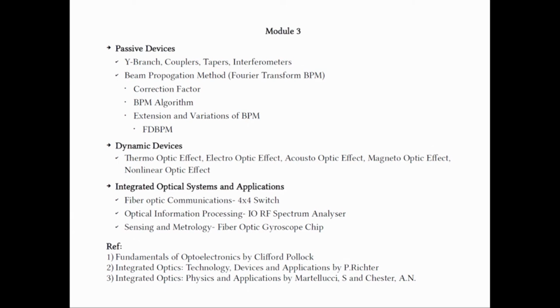They could be used for input output couplers, we can use the acoustic effect for doing a lot of optical signal processing. We can have signals, some of them could be attached to the electrodes, IDT electrodes, some of the signals could be associated as modulating signals to the light wave and so on, and we can find out many properties of interaction of the light waves and acoustic waves or the RF frequencies using the acousto-optic effect.